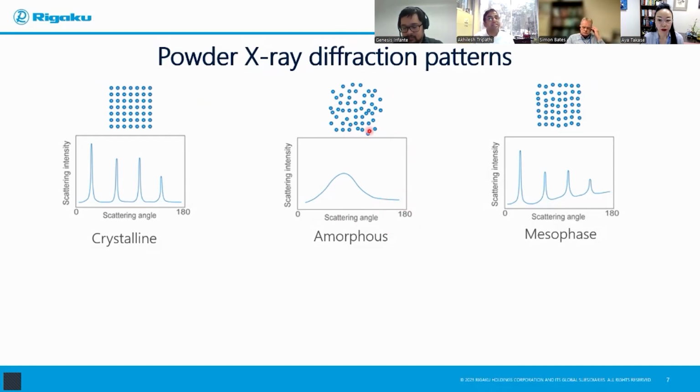There is no lattice, i.e. a repetition in the crystal form. It's a haphazard arrangement of atoms, and hence an amorphous pattern. Or you can have a mesophase, which is a state between crystalline and amorphous, exhibiting properties of both. It has some degree of molecular order like crystals, but also retains the fluidity of an amorphous material. It's quite common to see this sort of disorder.